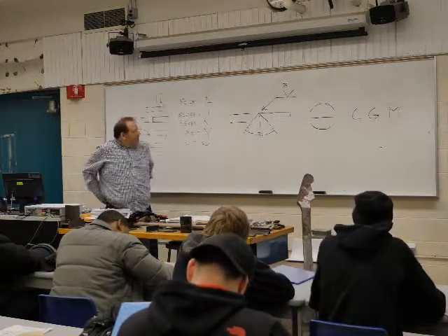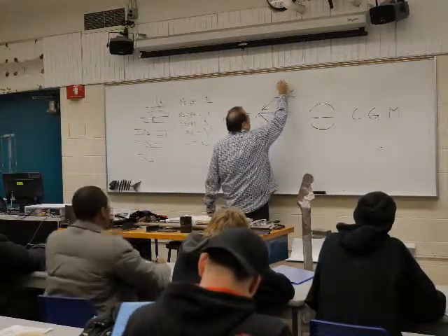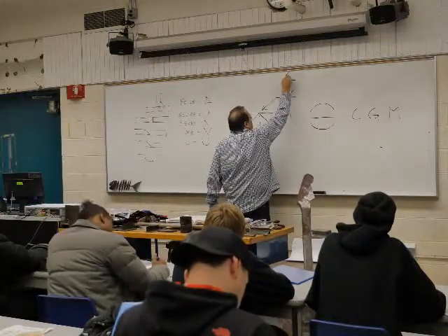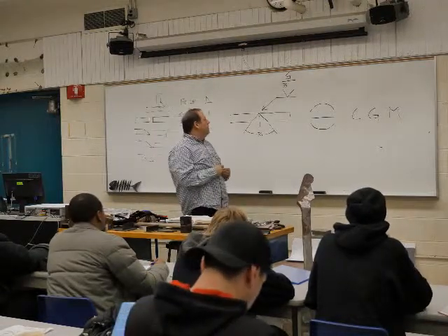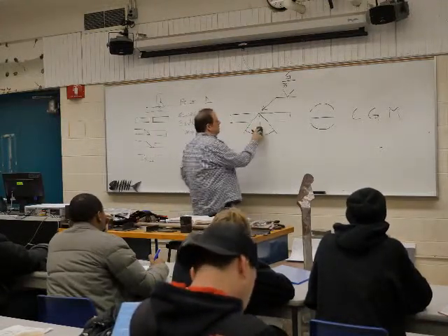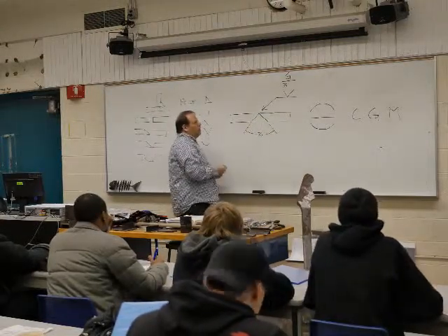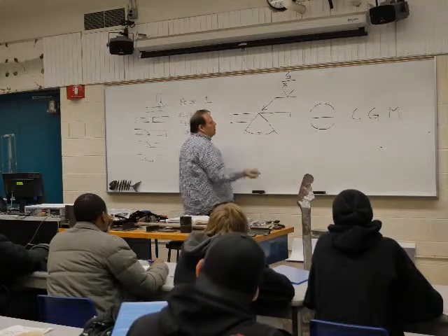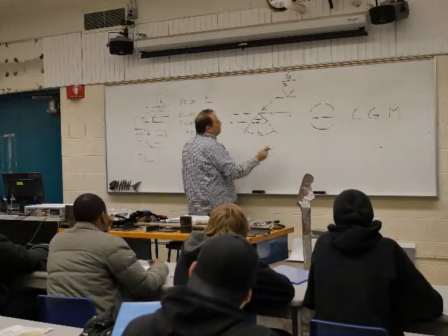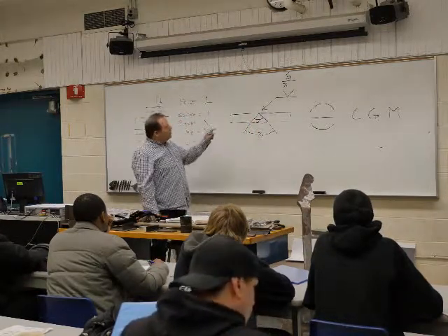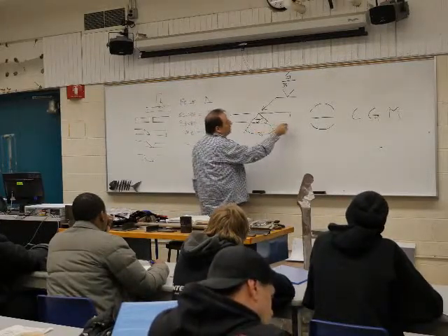So, if we stack a couple of these on here, we can then go here and here. We're basically just saying that it's a V groove, and when we weld it, it's a V with a 75-degree total angle. Our bevel's 37.5 degrees. You're going to grab your rod. You're going to run, say, a bead here, a bead here, and a bead here to finish that thing out. Now, if you look at that, this is the surface. This is a little bit higher than the surface.